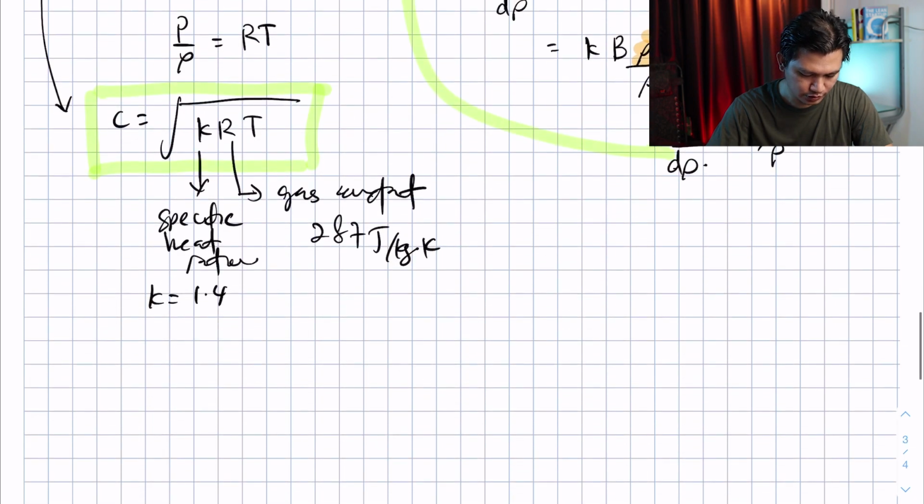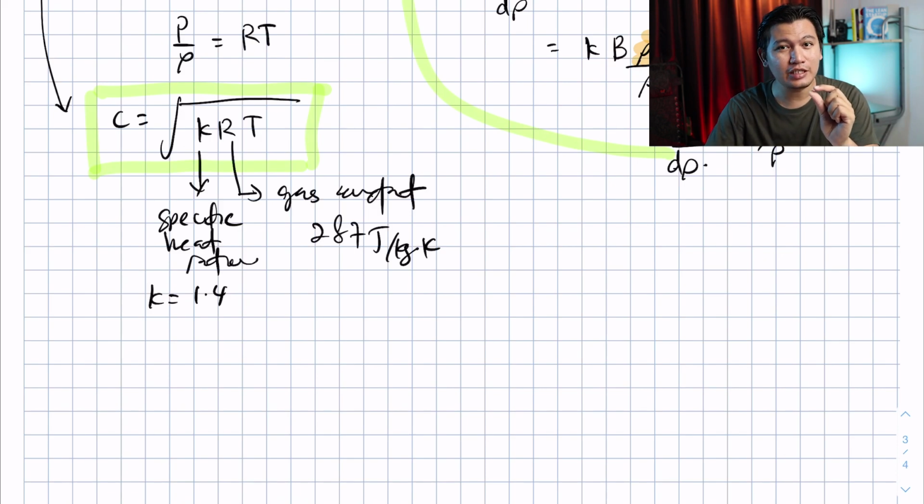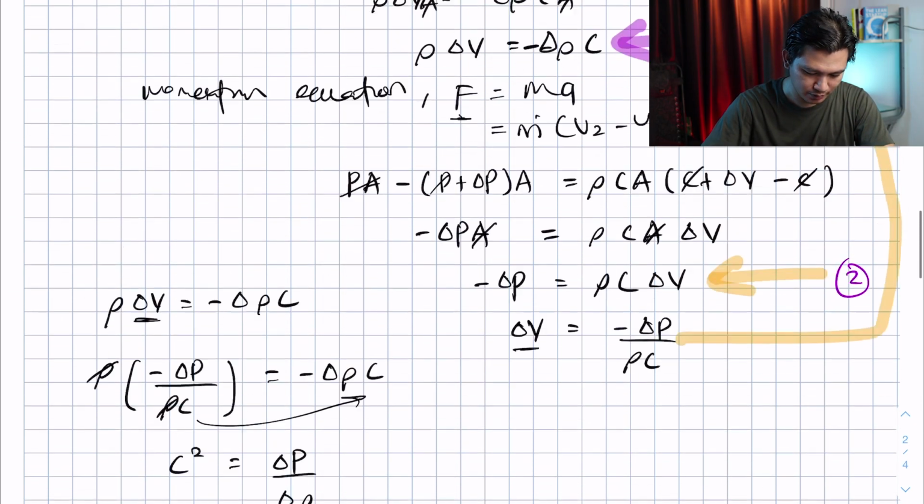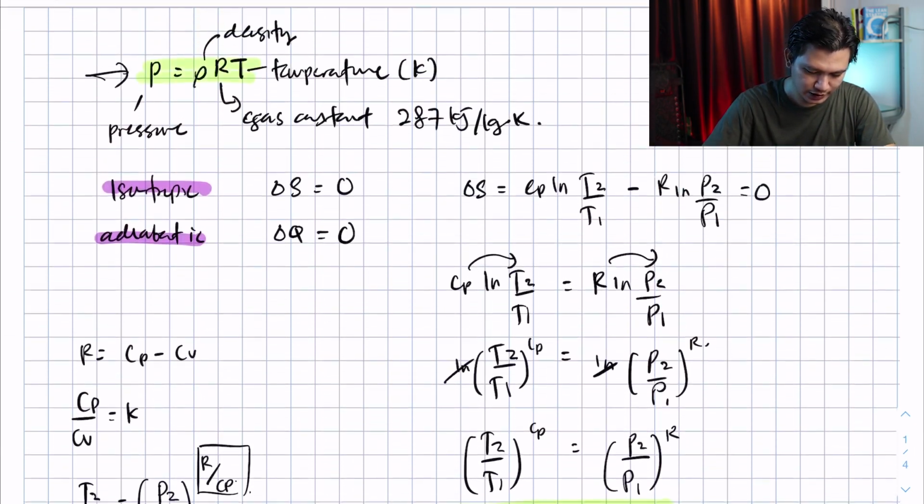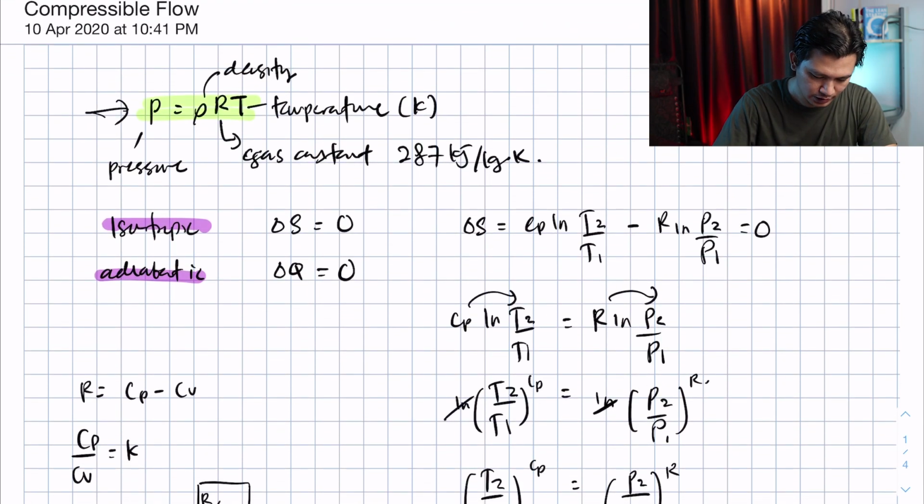Okay, so because this is 287, sometimes we use 0.287, but 0.287 if the unit is in kilojoule. And if you use joule, it is 287. So I may have made a mistake here at the very beginning. Okay, so here is incorrect. And I'm going to remove this and replace this with joule.